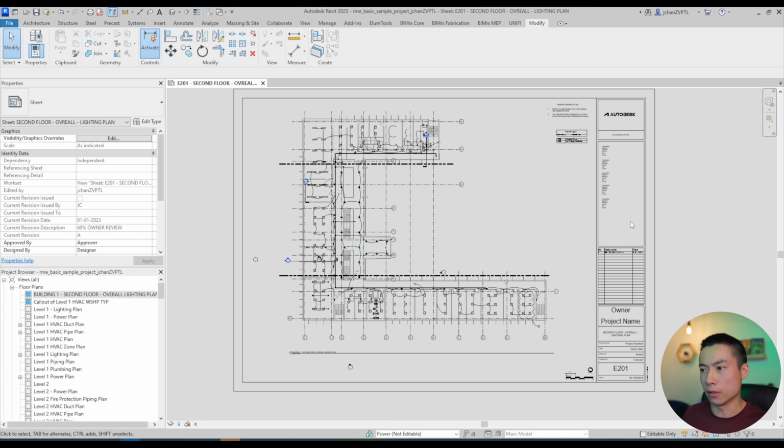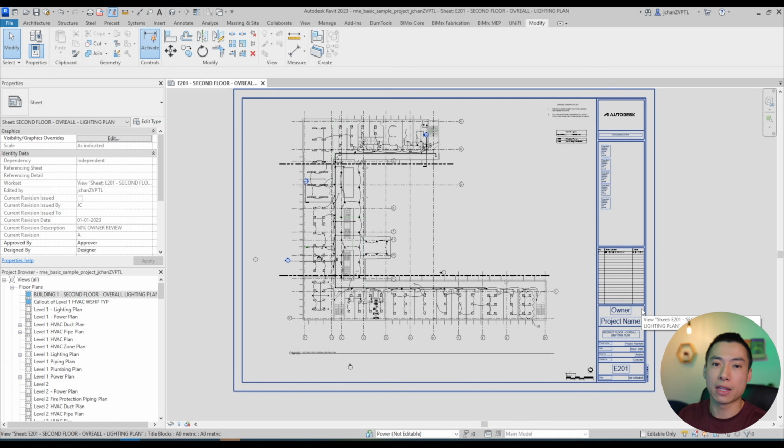Just one more note. Title block information tends to be on the right-hand side because, well, in the US, all of our drawings are typically bound on the left-hand side. So if you bind on the left-hand side, you don't want your information in the bound. So it's usually on the right-hand side, or sometimes the right bottom. Like it'll sometimes wrap around down here. So there's all different formats for a title block, but it generally has the same information.